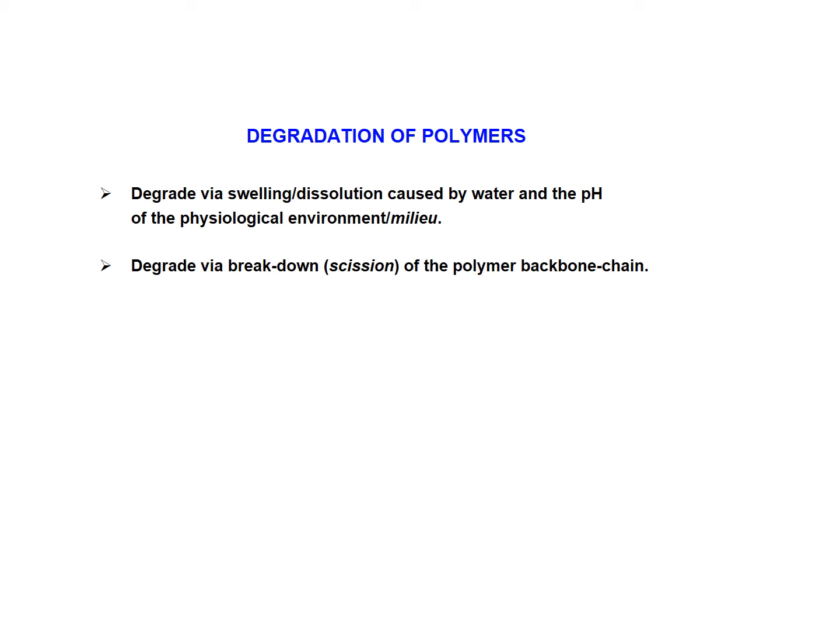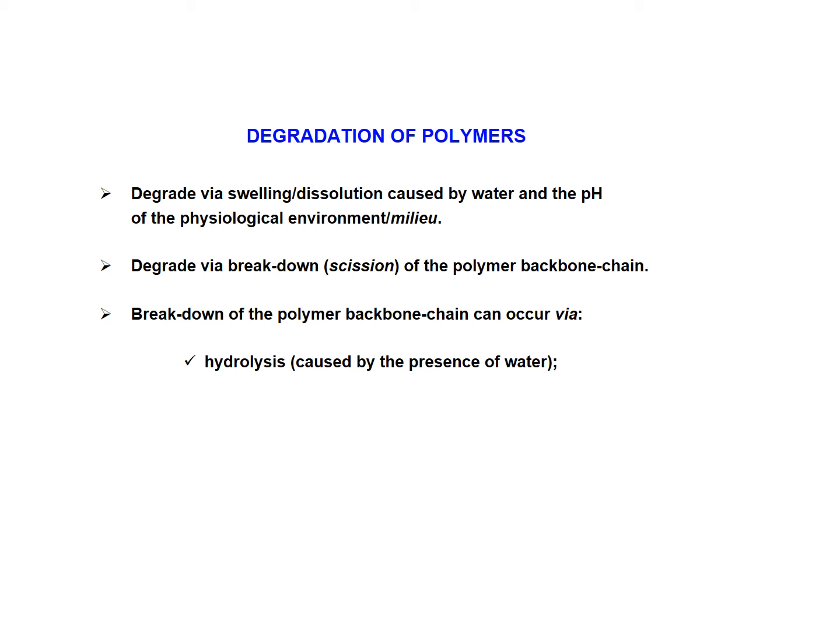They break down because the polymer backbone chain of the carbon atoms breaks down. This breakdown can occur through hydrolysis. This is the official term which describes the presence of water and the infiltration of water into the polymer environment, which slowly but for sure causes the swelling and then the breakdown.